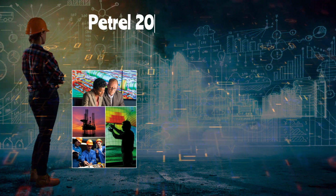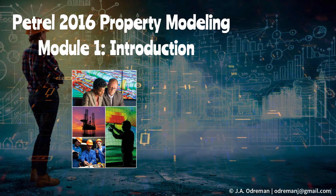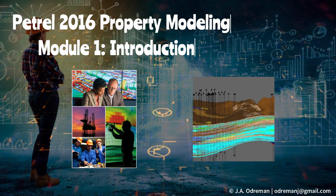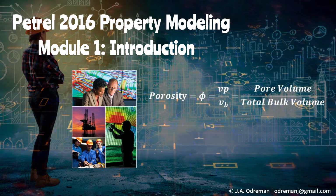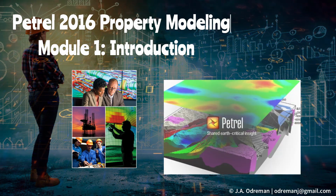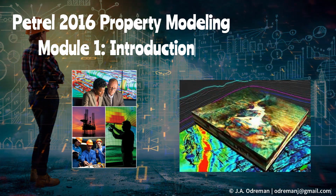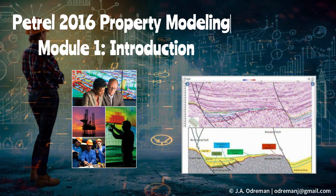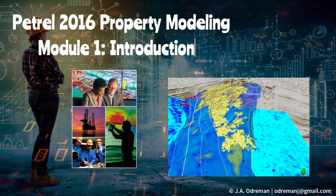Property modeling in Petrel is an essential module that allows geoscientists and reservoir engineers to create three-dimensional models of the physical properties of hydrocarbon reservoirs. By integrating well, seismic, and reservoir data, the software assigns key properties such as porosity, permeability, and fluid saturation throughout the geological model. Using advanced interpolation and simulation techniques, Petrel enables the visualization of the spatial distribution of these properties within the reservoir, helping teams plan drilling activities and optimize production. This integrated approach provides a powerful tool for managing and maximizing efficiency in resource exploitation.